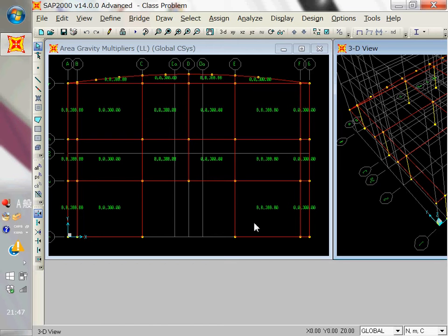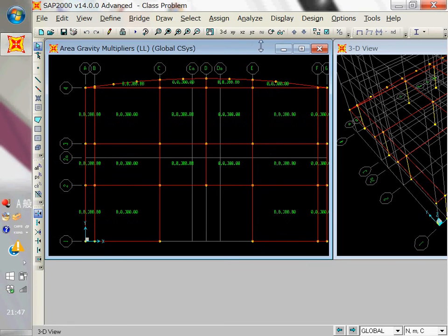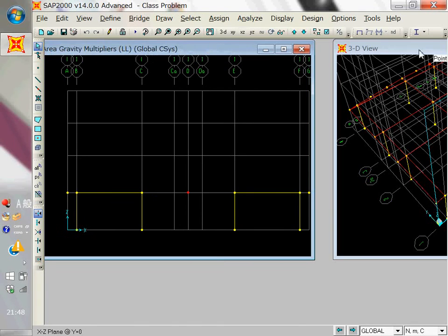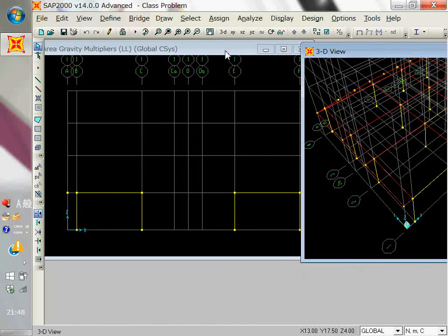Once you have provided the shear wall, you can delete these grids or you can hide these grids because we don't want to see them. How can you do that? I told you that we cannot draw the shear wall in the plan, so we have to go to the elevation. So let's go to the elevation 2A. It will be the XZ elevation, and then go to 2A.